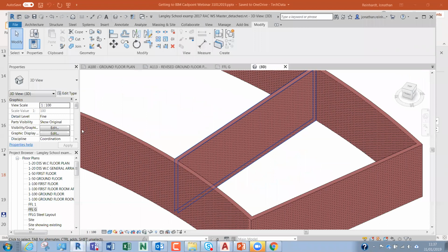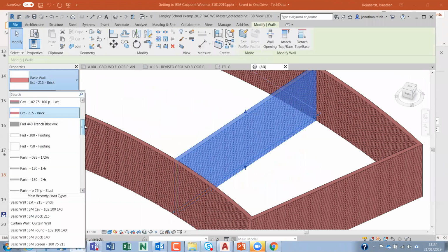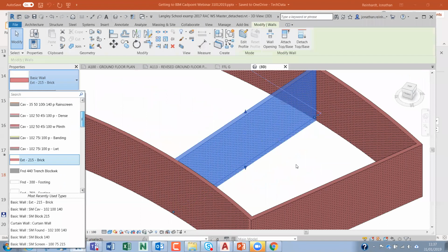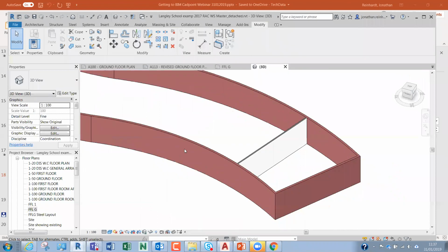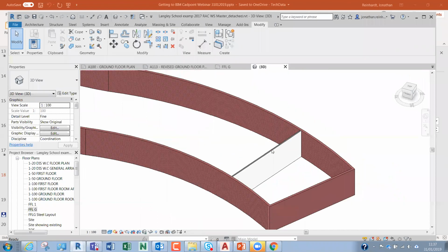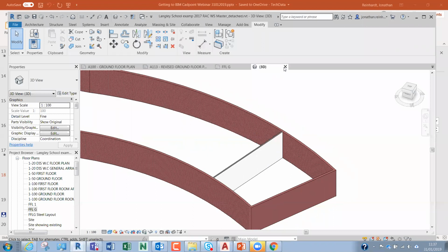I can then go back to my wall type, and I can select, okay, well, I want a partition or a 2-hour partition or stud between that. I can just click on that, and that wall type has automatically changed to that as well. So I suppose the power of this is that you're also able to then further take this information and create something called schedules. And I'm going to show you an example of a schedule using our windows as well.